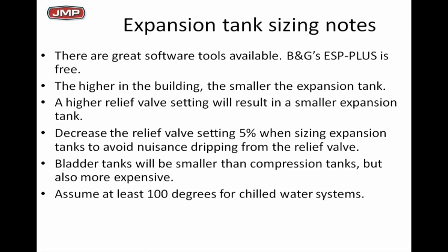Keep in mind the higher in the building you put the tank, the lower the pressure will be on the tank. So remember, you've got Boyle's law you're working with, so the smaller the tank. Remember, the higher the relief valve setting you can put on there, the smaller the tank. Remember we're working with Boyle's pressure ratios. So the higher the max pressure we can have is that relief valve pressure. So the higher the relief valve pressure you have, the smaller the tank.